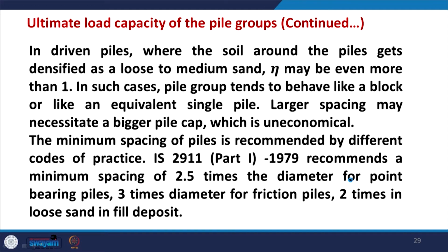If you increase the spacing between piles, the value of eta, or group efficiency, may increase, that is good. However, at the same time it will require a large size of pile cap, and that may be uneconomical. So simply we cannot keep more spacing to get a higher value of eta; rather, there will be an optimum value of spacing between piles,